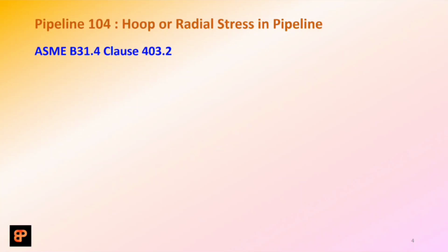But when there is a stabilized oil or water or liquid services, then we use ASME B31.4. The basic criteria is that the services covered under B31.4 are considered less critical as compared to B31.8 services, and therefore you will find one difference.